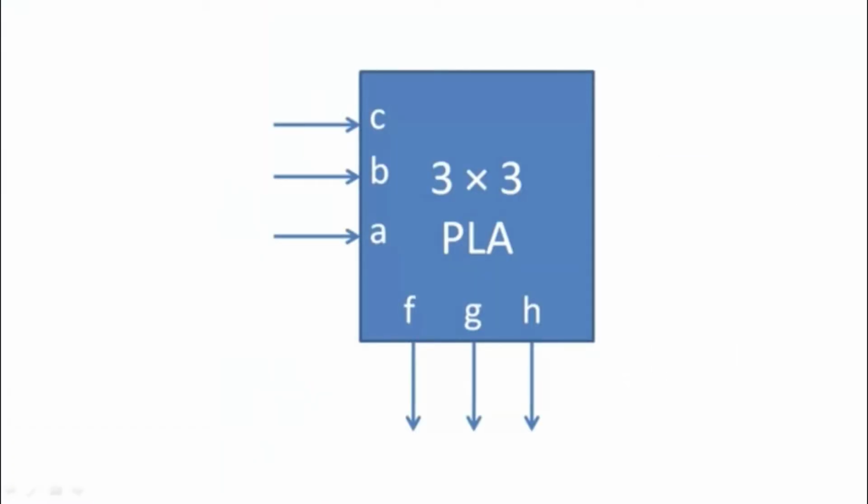To demonstrate why full circuit minimization is hard, we will discuss the Programmable Logic Array, or PLA. A PLA can be implemented in much the same way as a ROM, except that we want to create a minimal circuit design for several circuits at once. Hence why we describe the size of the PLA according to the number of inputs, rather than the number of addresses.